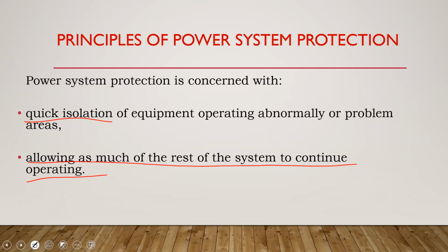Now, coming back to your home, let us say that the breaker that's controlling the kitchen does not operate. Then it means that the fault would no longer be just localized to that circuit. It now becomes a fault for the entire panel. And so your main breaker may trip. Now, if your main breaker trips, what that will result in is that power will be lost for the entire house. All right? Now, the same is true for your power system. If you're unable to isolate,